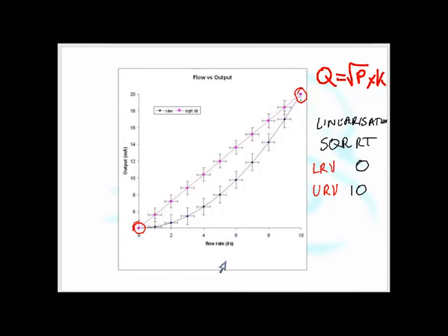Now, unfortunately, if I do what's called two-point calibration, which is lower range value and upper range value, then if you look at those 2 points, both of these graphs are the same. What this means is that at install, if I incorrectly choose the wrong type of linearization, I won't realize.